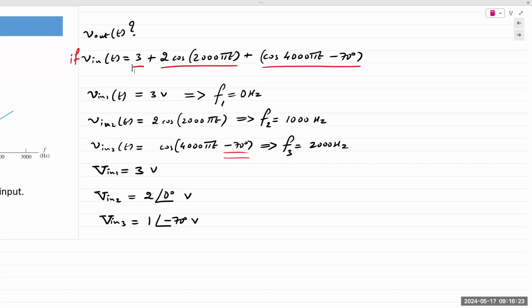Does that make sense? There is an addition sign in there, but mathematically speaking, we cannot add or subtract if the frequencies are not the same. So in general terms, the purpose of the plus sign is simply and, the word and, A-N-D. So once we have a signal like this, break it up into individual parts, V in of t, V in 1, V in 2, V in 3. We write out the individual ones and we extract all of the information, meaning we extract the peak values, the magnitude, the frequency information, and the phase angle.